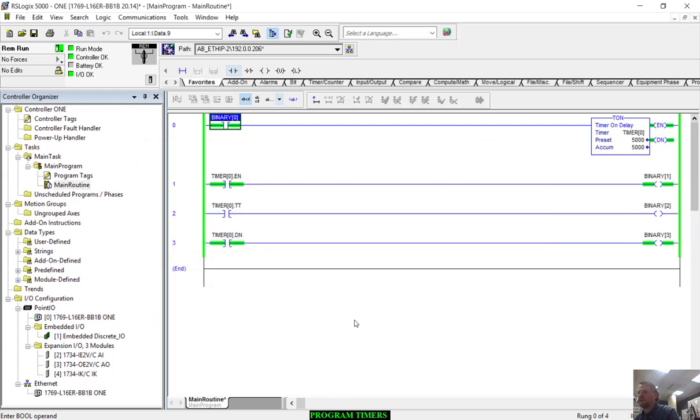So I want you guys all to get a solid understanding that troubleshooting in a PLC can be done in the data table, and sometimes a whole lot easier than in the ladder logic, because you can look at multiple bits from one location. So keep this in mind when you're developing your code. If you do a good job organizing your code, you can use a data table to help troubleshoot larger portions of code faster.